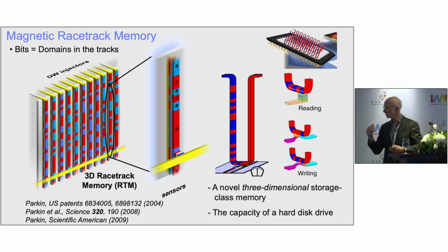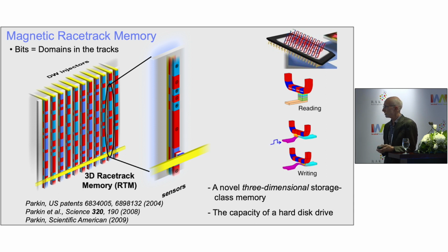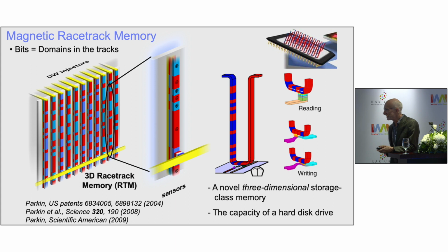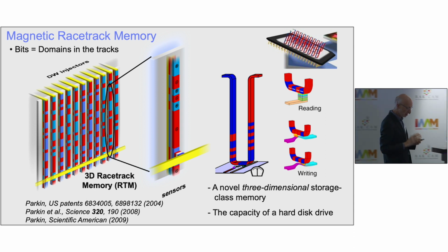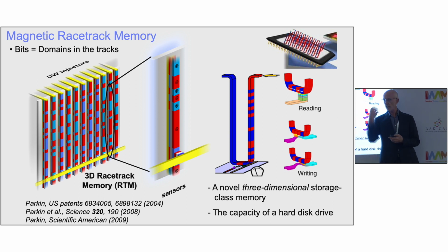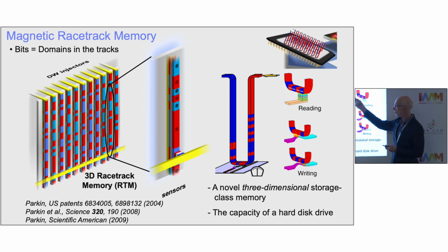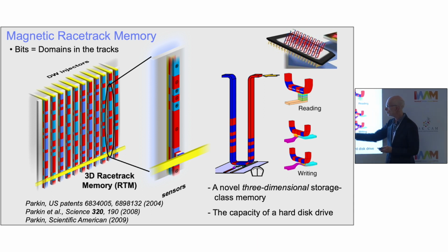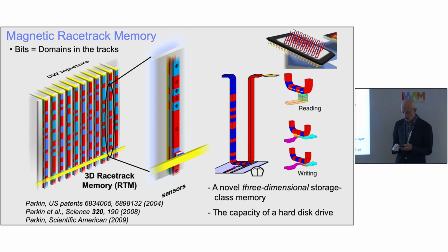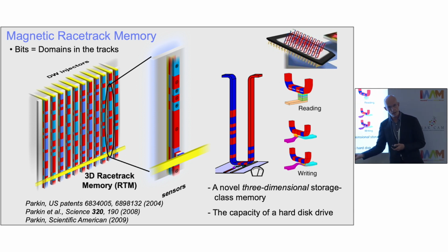And we do that by using a phenomenon of current. When the current is spin polarized, it carries spin angular momentum, and we could use this to manipulate, in particular, the domain walls that you could see in this cartoon. If I go backwards again, then you can see here in this magnetic racetrack, and I'm going to show you briefly, we've now reduced the size of these racetracks to approximately 50 nanometers in diameter. These are domain walls which are approximately 6 nanometers in width, and by passing current pulses, the concept is that all of these domain walls will move in the same direction, and today at speeds exceeding a few kilometers per second, to reading and writing devices incorporated into the racetrack.